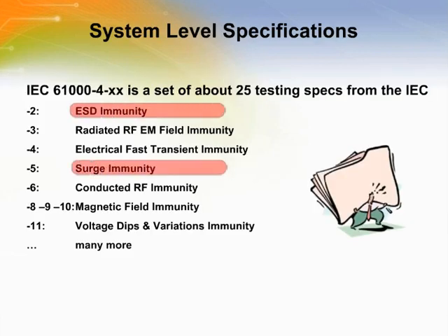IEC stands for International Electrotechnical Commission. Out of these specifications, TI regularly tests the -2 ESD immunity test and started to test the -5 test for surge immunity. If it comes up as to why we don't test the others, it's because we haven't found it necessary. If someone is interested in knowing how devices perform under certain standards, TI would be happy to suggest it to the team to see if they would be willing to attempt it.